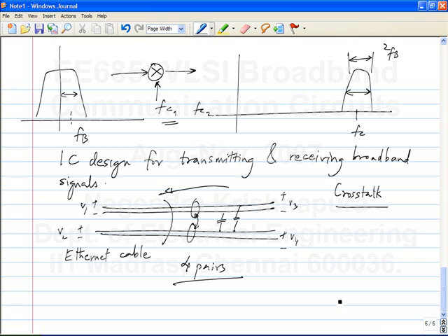So that is another reason why, if you just connect one side to the computer and put one of the other pairs on an oscilloscope, you will see total garbage. Firstly, it's because the wire itself is so long and whatever you transmit on that particular pair is not being received properly. And secondly, what is being transmitted on the other 3 pairs also gets coupled to this particular pair. So this is one of the problems.